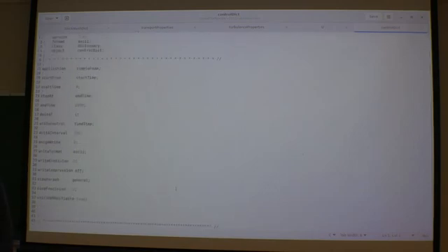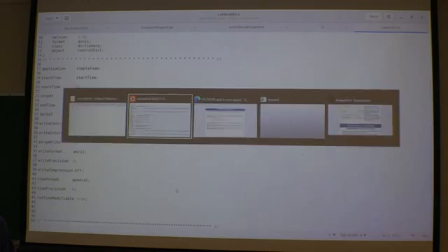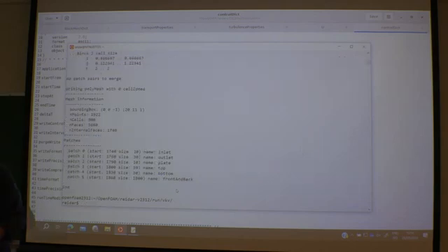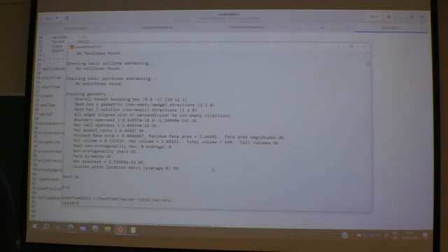So let's try to run that one and see what happens. First, blockMesh, of course. Inlet, outlet, plate, top, bottom. I don't have that many cells, so it's not a big case. It's a good habit to always run checkMesh.